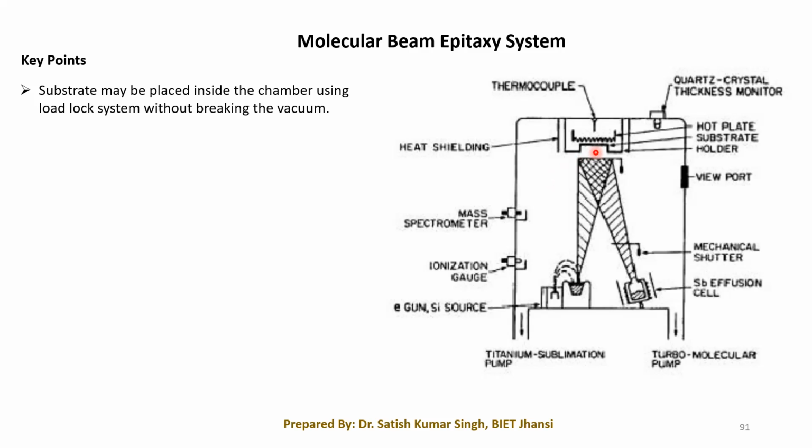The second way is sputter cleaning. In sputter cleaning, we take argon gas, an inert gas, and a beam of argon is bombarded onto the substrate.